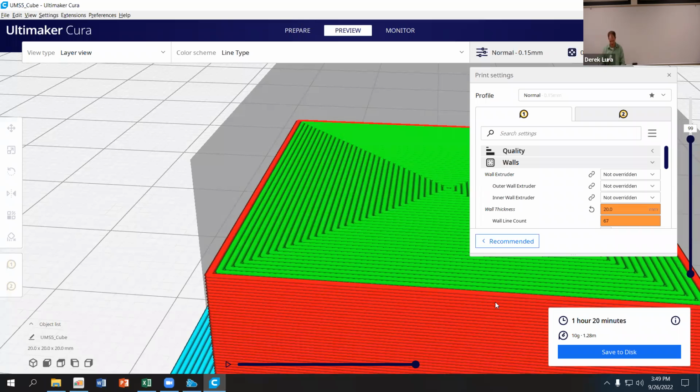Even in a part like this, this part has 2 walls, 2 lines for each wall. So each wall is actually 0.8 millimeters. And I can get pretty good rigidity out of a part like this if I make sure that my lines here, like my width, the height of the wall, is not too long. And I use features inside the part to add some stiffness, right? So you can make pretty reasonable parts that are pretty stiff.